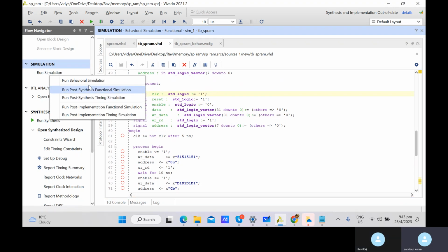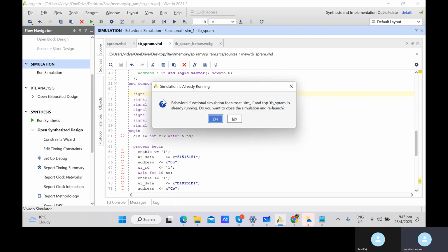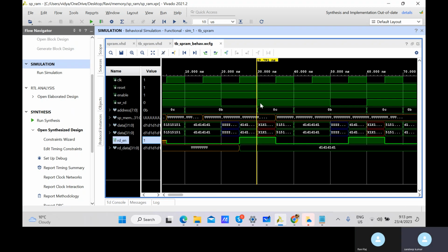Currently in the simulation, the signal from the test bench is changing on the negative edge. If I do this change on the rising edge, this read enable will also appear exactly here internally, so it will not show the issue.